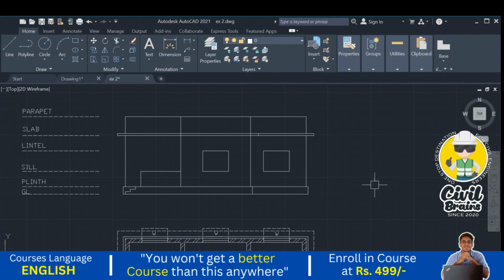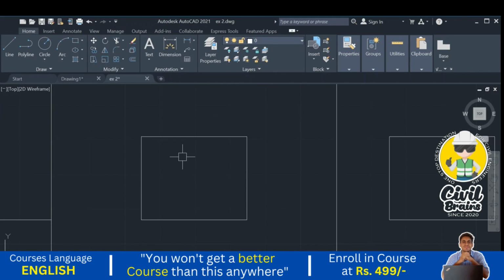Now you can give the design to this. So we can give different designs for the elevations. We can give the designs, all those things. Okay, so window will be there. So window I just offset, not 0.15, offset 0.1. That is the thickness of the window frame I'm considering, and I'm doing this one.